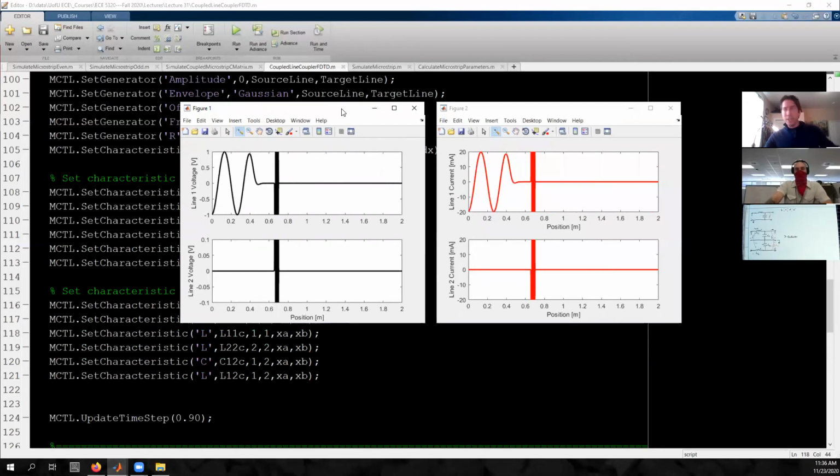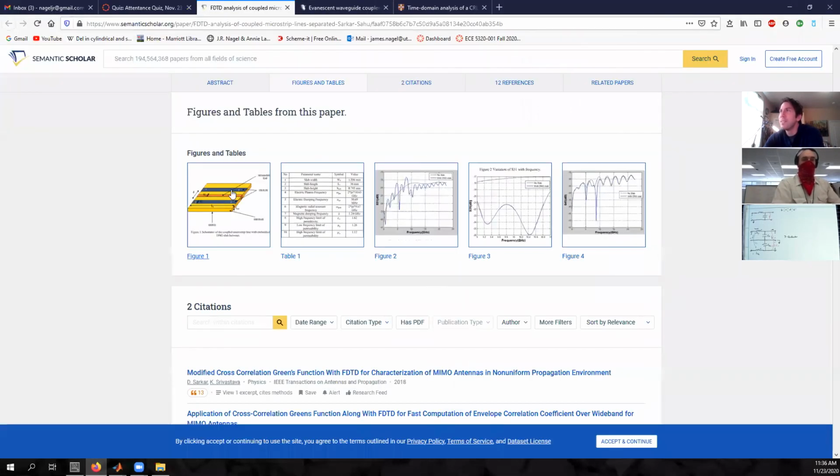And then what would be extra interesting is I don't know if anyone's actually done a model this way before, using multi-conductor transmission line with these electrostatic models to try and design a coupler. From what I could tell, most models seem to use some kind of full field simulation. Right, so you can see here is an FDTD analysis. I'm willing to bet if you dig into this, they probably did kind of a full field version of this, a full three-dimensional FDTD kind of simulation of that.